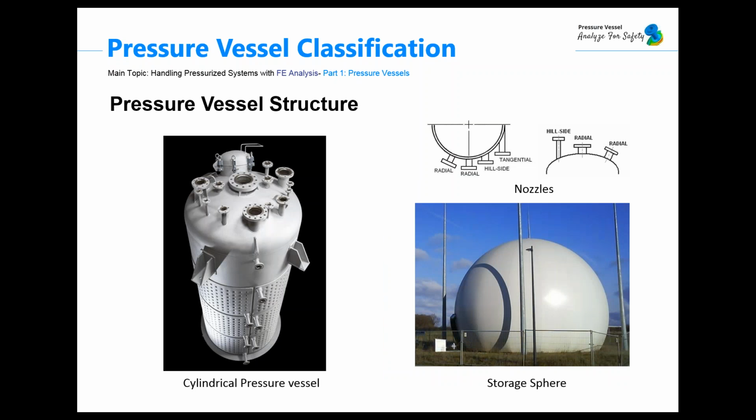Considering the shape, theoretically pressure vessels can be almost any shape, but shapes made of selections of spheres, cylinders, and cones are usually employed. A common design is a cylinder with end caps called heads. Head shapes are most often round, circular, or shaped like a dish. More complicated shapes are more difficult to analyze for safe operation, and they are usually far more difficult to construct.